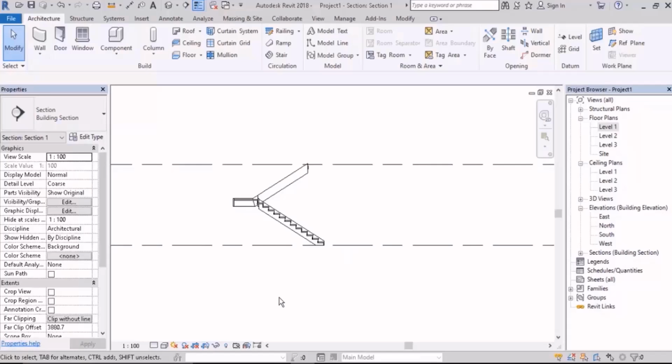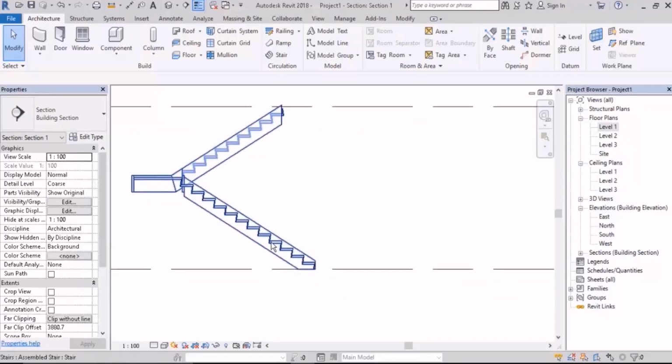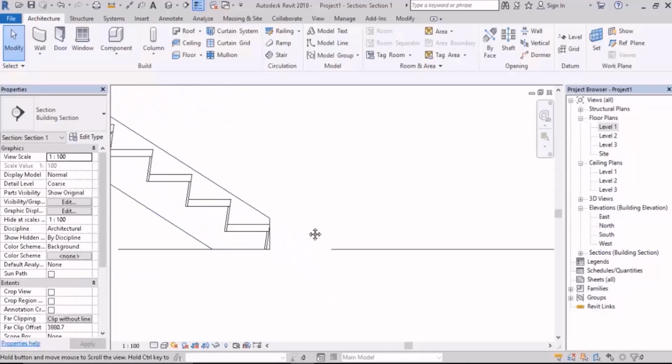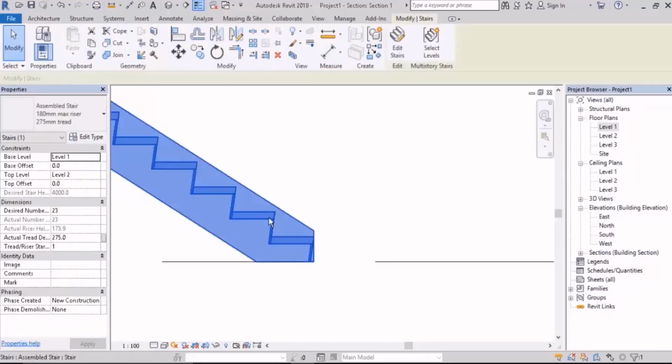And this box you see is half. We need to talk about it, is crop. But so that it doesn't stop you from working, you need to click on this don't crop view and then the view opens and then click on the lamp to remove the box. We will discuss it later. For now, our focus is only on stair. Well, I zoom in a little.